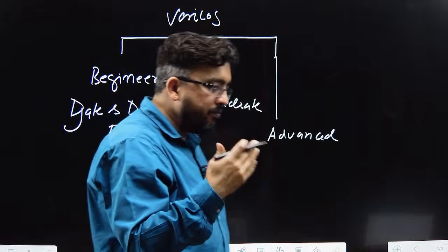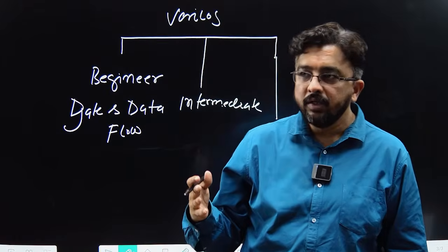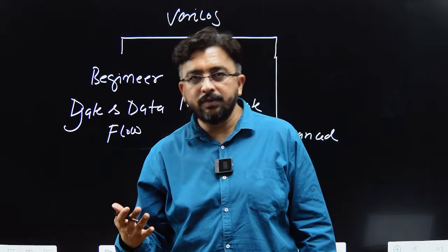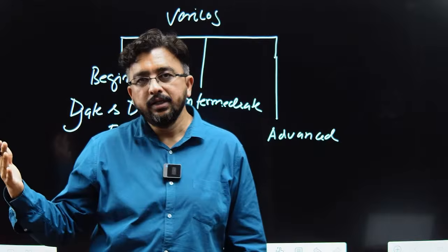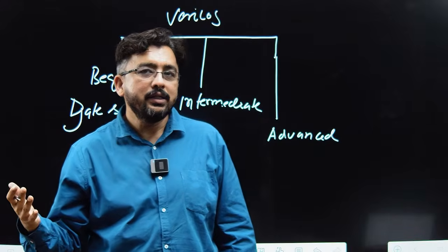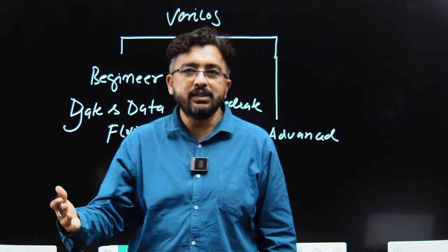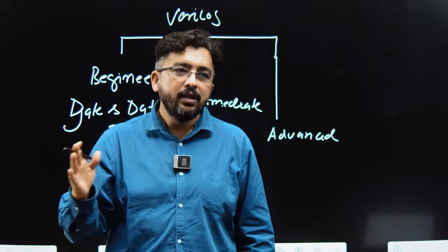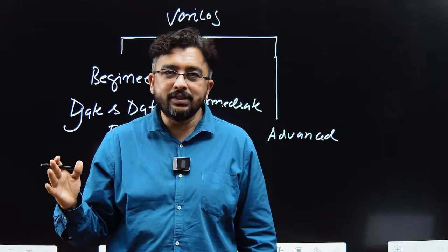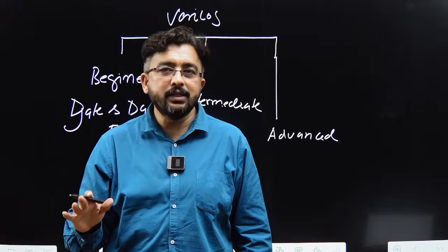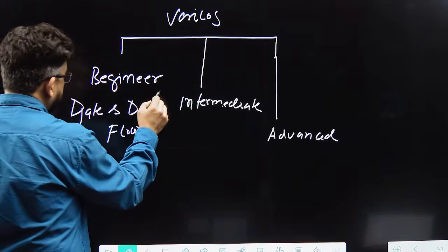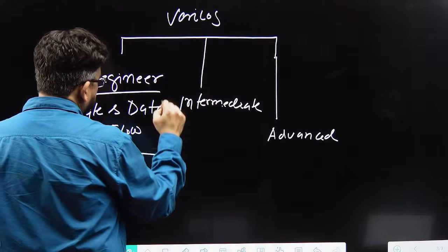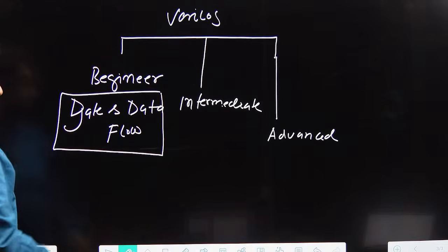If you have a basic understanding of the hardware up to your counter, shift register, you can design any counter, any shift register, or any type of multiplier circuit, divider circuit, adder circuit, full adder circuit with the help of these two modeling. So gate level modeling is very important.